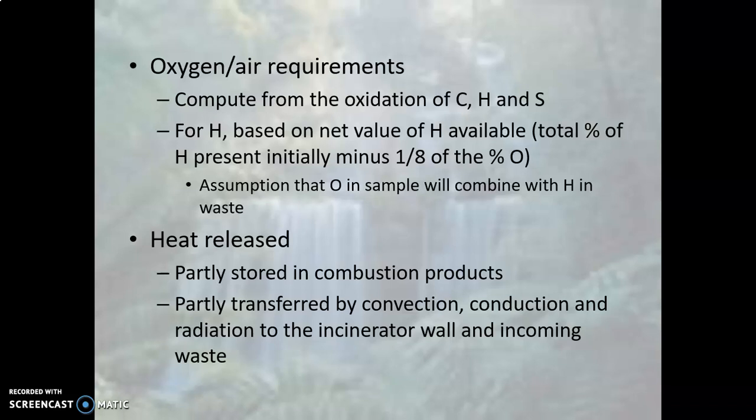which can be calculated from the oxidation of C, H, and S. While heat is released from combustion, some of it will be stored in the combustion products, and another part will be transferred by convection, conduction, and radiation to the incinerator wall and the incoming waste.